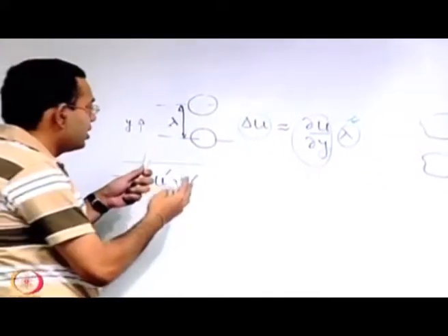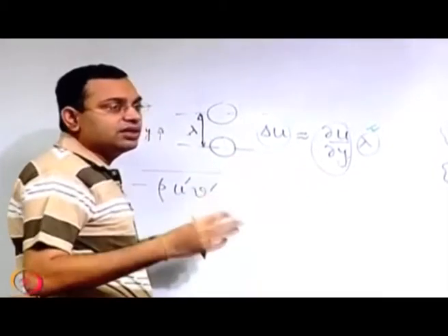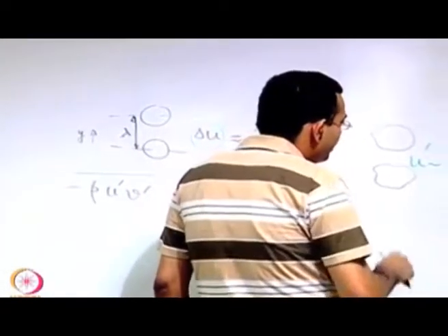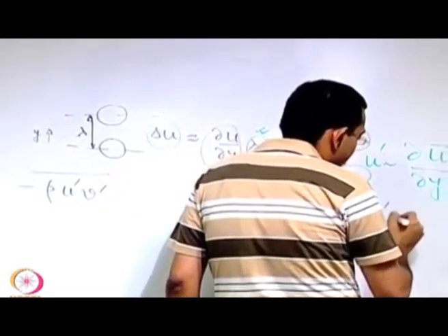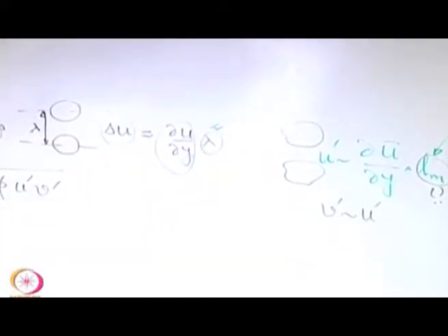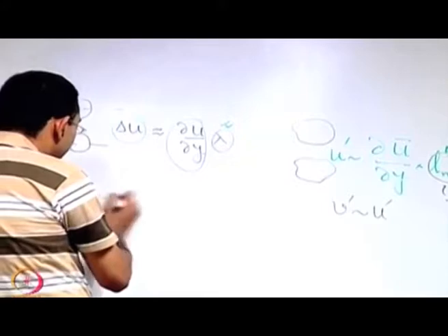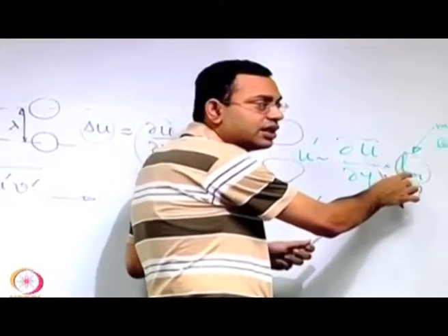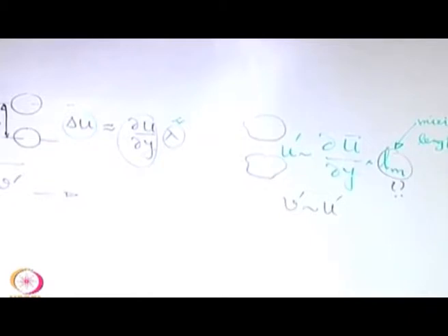He made a desperate attempt at writing it in terms of some equivalent quantity which is sort of a pseudo-known. So you have this u prime, and what Prandtl hypothesized is that, in terms of order of magnitude, u prime and v prime, the fluctuations, should be equivalent. It is an attempt of writing it in terms of a scale, not really, because you do not really know what this correct length is.